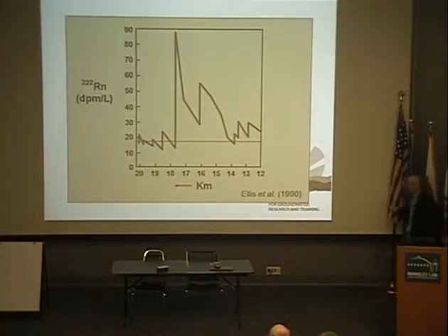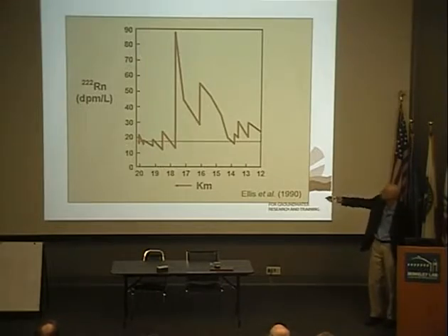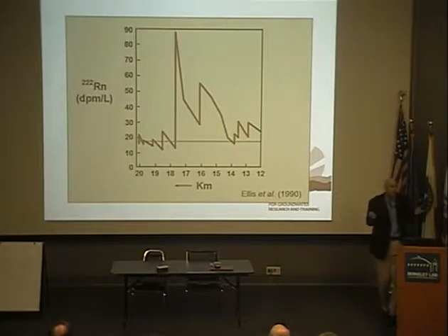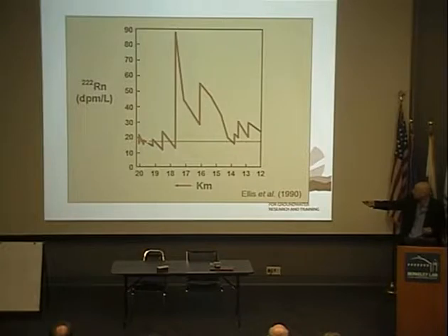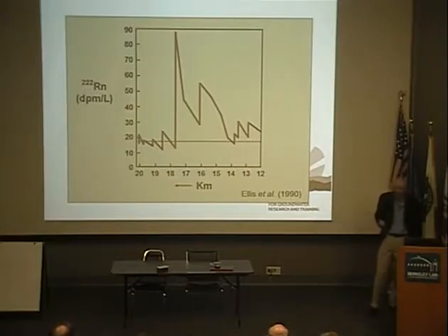This is one of the earlier studies. This, I think, was in South America, work of Ellen's. So this is moving downstream in this direction. Radon concentrations, and you can see the dotted line is the background concentration at that time. So essentially no radon here. Big peak in radon as groundwater enters the stream. Then it's lost. Some more comes in, and then it's lost again below that. So indicating very clearly the points where groundwater is coming in. This was over about 8 kilometres.